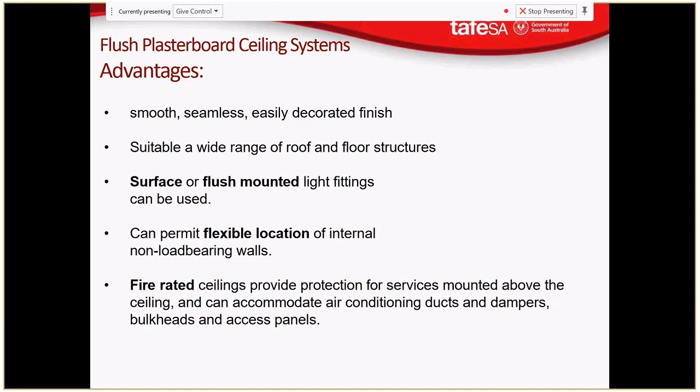But one type of metal sheeting I have seen a bit of, and something which is actually quite desirable from a historic perspective, is pressed metal ceilings. Has anybody seen pressed metal ceilings in old buildings? Typically you've got thin sheets of metal, probably around 0.48, 0.6 base metal thickness, that have been embossed with pictures.